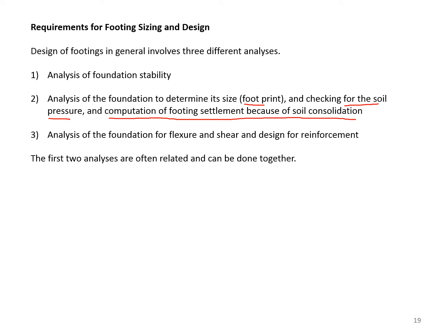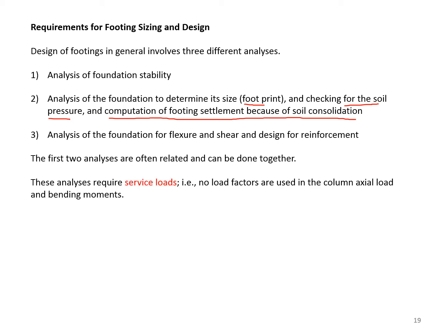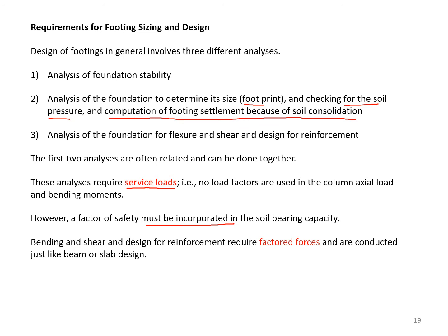The first two analyses are often related and can be done together. These analyses, the first two, require service loads. In other words, no load factors are used in the column axial load and bending moments. However, a factor of safety must be incorporated in the soil bearing capacity. Bending and shear and design for reinforcement require factored forces and are conducted just like beam or slab design.